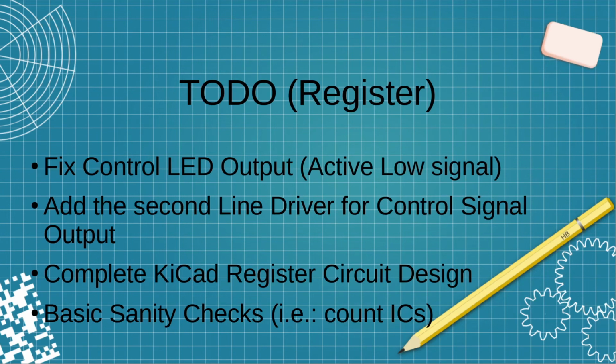In the interest of time, we'll leave the video there. There's lots to do still. I do have to fix the control LED output. I have them wired up in KiCad as if they're active high. They're really active low, so I need to make changes for that. And there needs to be a second line driver, and I need to separate those signals.